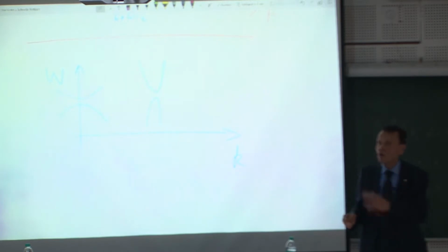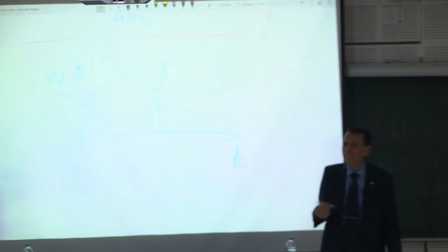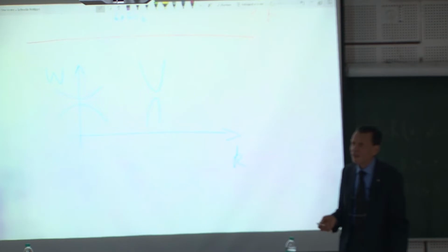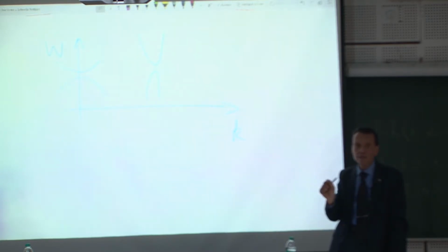Okay, but all these have been exhausted up to, say, 30, 40 gigahertz. What can we do to generate? Not to amplify, to generate. You have another technique which is called frequency multiplier. So you can make use of a very simple nonlinear diode. And if you have nonlinearity, you have harmonic generation, and you can input, say, 10 giga, and adjust the operating point to, say, maximize the third harmonic or the fourth harmonic.